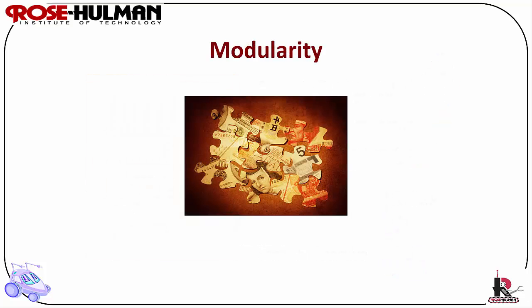Modularity refers to what are the components of the control system. What can talk to what? Modularity refers to the way the control system is broken into pieces, components, or modules. Modularity also refers to how the modules interact with each other to produce the robot's overall behavior.